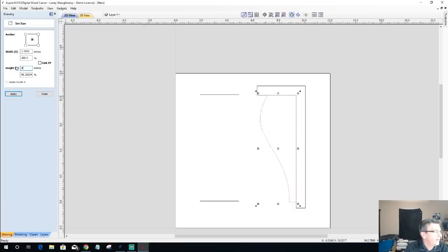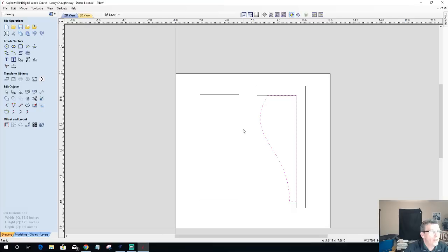Let's get rid of that other 8 there. Just bring it down just a little bit so it has that overall height. And the curvature or the width of this is really going to represent how thick my part is. And I want it to have an overall thickness of that 2.5 inches, the thickness of my material.